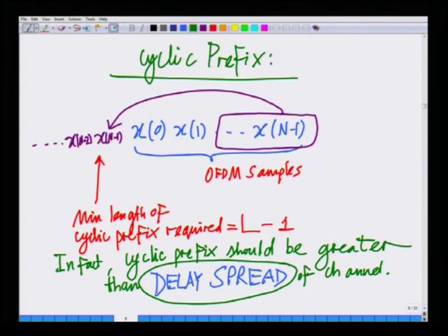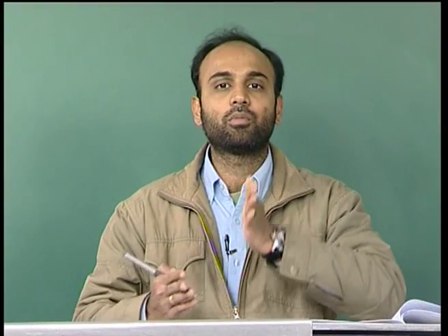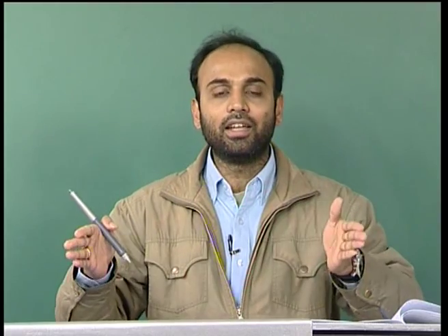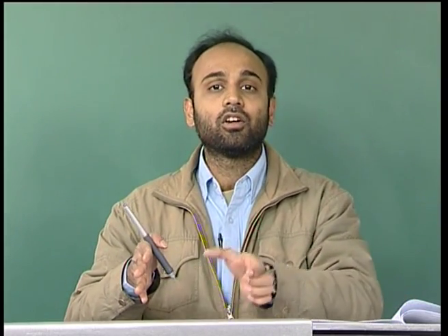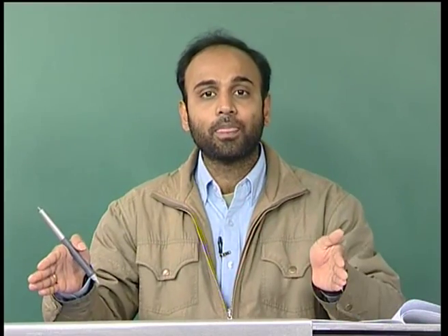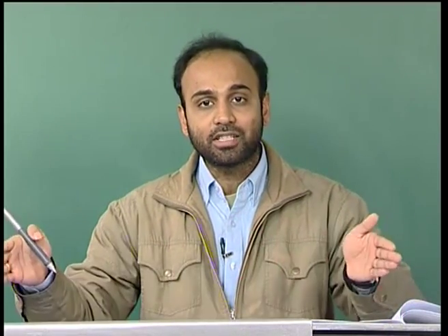This is key. Remember, we said in a wireless communication system the channel has a delay spread, that is, energy is not arriving at a single point of time, but it is arriving in a delay. That is what gives rise to this intersymbol interference and this FIR filter of channel taps of delay spread L, because signal energy is arriving across the spread.